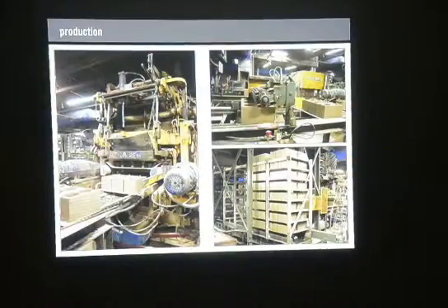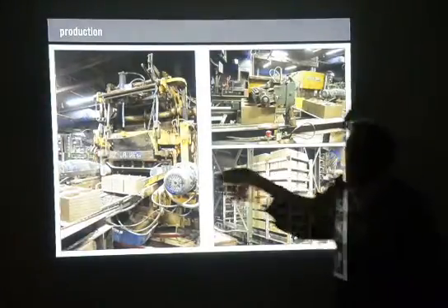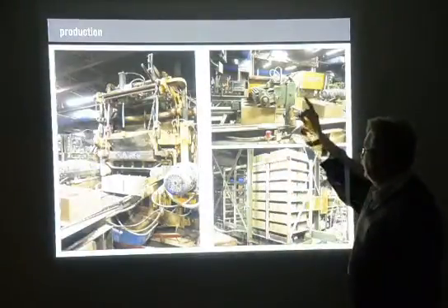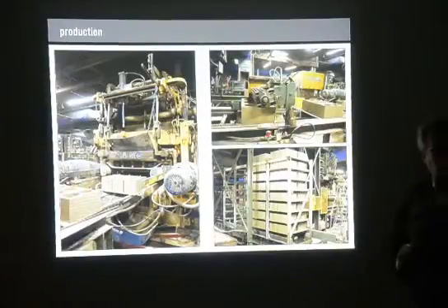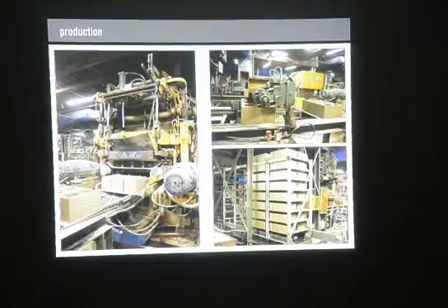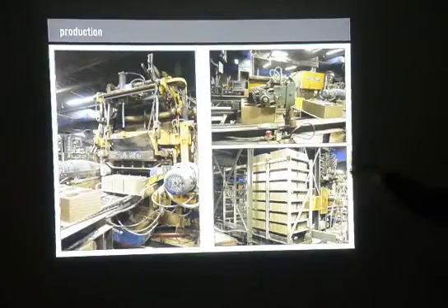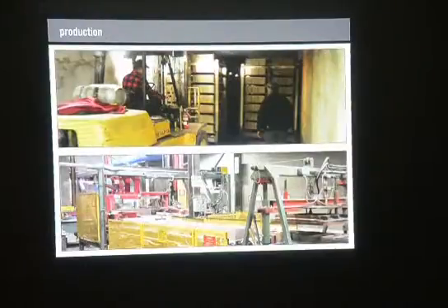But the key here for production is not only the quality and consistency of the mixing, it's also how it's vibrated and how it's compacted, okay? So the key to get that 1900 PSI compressive strength or the 2000 PSI compressive strength that we have today is 2 things. It's vibration and compaction. Without vibration and compaction, you wouldn't get the proper compressive strength. It's the same for high strength, 3,750 compressive strength, you need that too. So all these things are very, very important, that quality control is made properly.